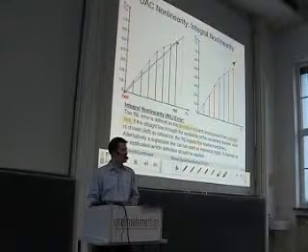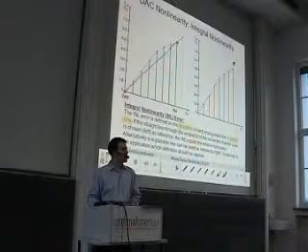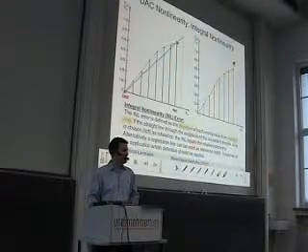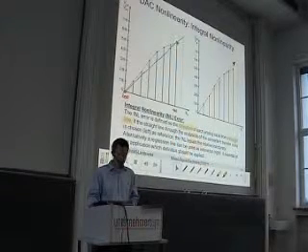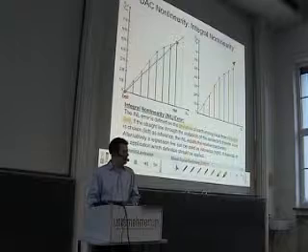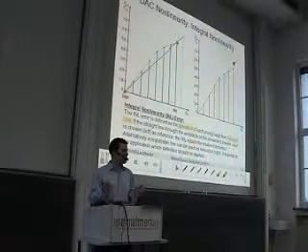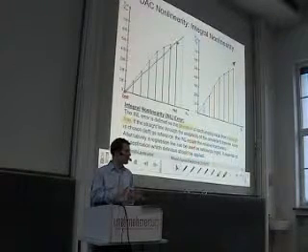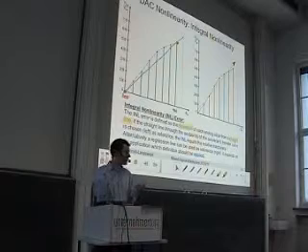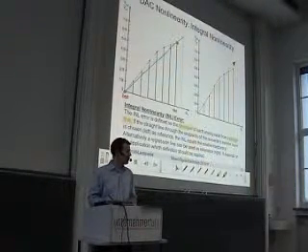This is a good definition that you can use if you measure the nonlinearity with a computer tool like MATLAB. When you can do a real calculation, then you can use this regression line. If you have a plot of your characteristics and want to estimate the nonlinearity, the first definition is much easier because you take a ruler, connect first and last point, and simply find the deviation.